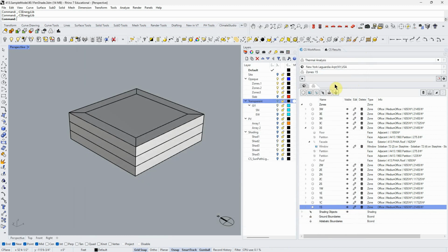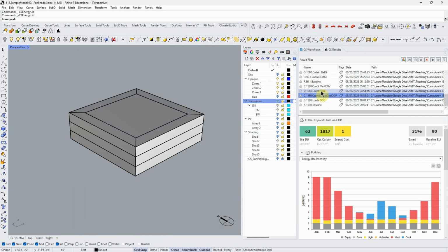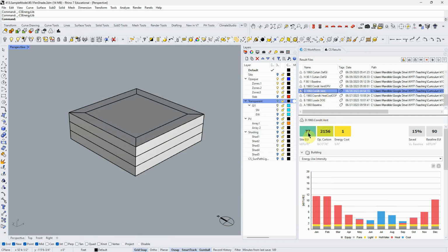And the result was a pretty substantial increase in our EUI, and that makes sense. Now we're bringing in fresh air from outside, so it's 32 degrees outside, 68 degrees inside. We're going to lose heat that way, and we're also going to lose cool if we've got it 68 inside and it's 95 outside. So that's not an efficient way of doing it. But I'm sure the baseline building would have had windows and probably a ventilation system, but it would not have had anything efficient. So this is realistic in some ways, though we still don't have windows.